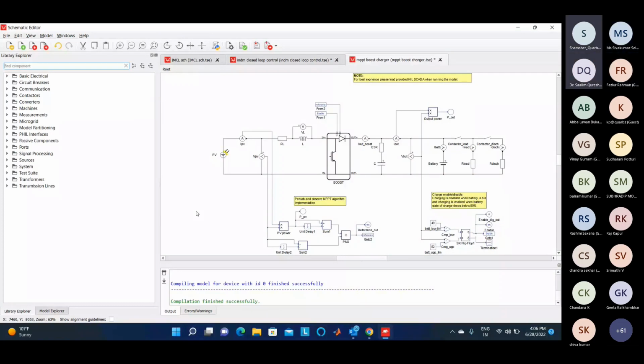More to add to what Shamshad Ansari sir said, as you are talking about multiple controllers, one for PV and one for wind, you need not worry. You can design a single subsystem for each controller and generate the C code for each individual controller. For example, for a PV controller you have a subsystem of PV in MATLAB. Generate its C code and export these C files into the Typhoon HIL advanced C function of the PV controller.